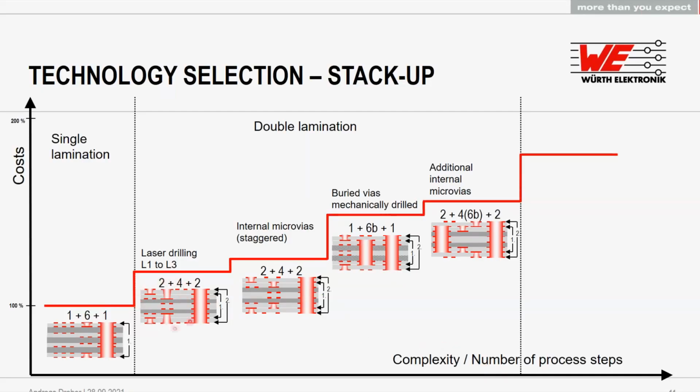As mentioned before, in the design rule, it is possible to have microvias from layer 1 to 2 and also from layer 1 to 3. The stack up has to be fitted to this structure. Not all combinations are possible, but you create an additional routing layer, which can definitely help with the fan out. Another option is to use 2 different independent microvia layers. We have to go through an additional galvanic process for the inner layer, so the cost increase is shown here.